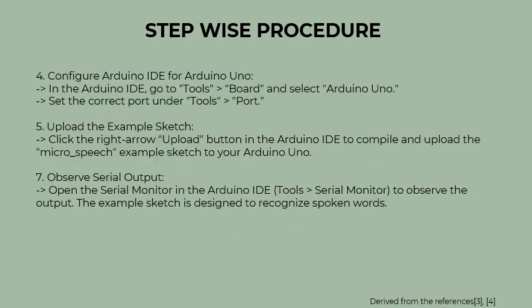Next, configure the Arduino IDE for Arduino Uno. In the Arduino IDE, go to Tools, Board, and select Arduino Uno. Set up the correct board under Tools, then Board.